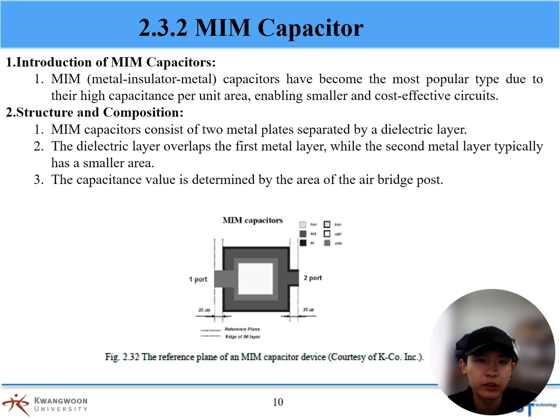The benefits of MIM capacitors: MIM capacitors help minimize fringing fields to ground and shorts between the metal layers, enhancing circuit performance. The inclusion of air bridges further reduces parasitic capacitance.